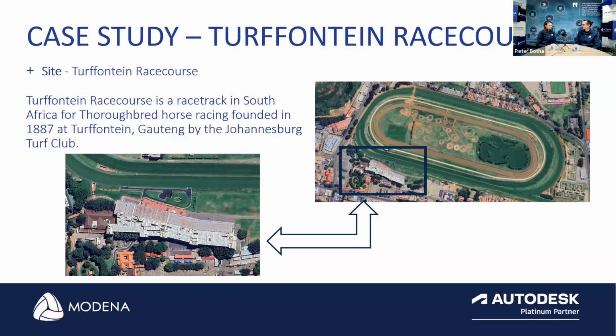Definitely possible. And also, there's normally not a lot of lighting in ceiling voids. Would that affect us? Yes, that will be quite a dark space to scan. We just turn off the camera option of the scanner and do a laser scan without it, so we are presented with a grayscale point cloud. The Focus scanner can scan in 2% light, which is really little light.